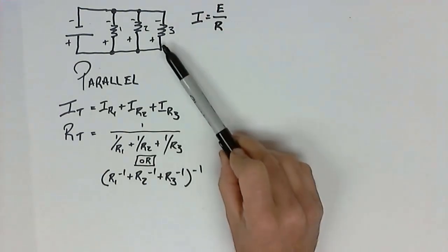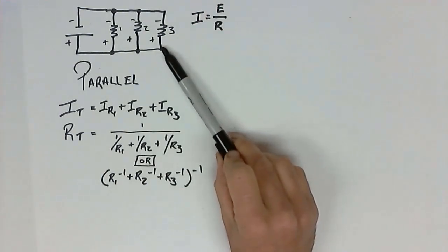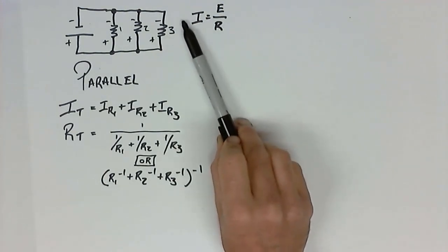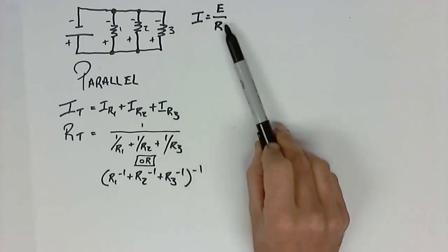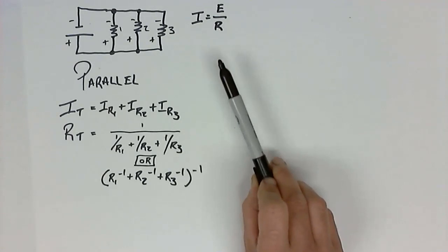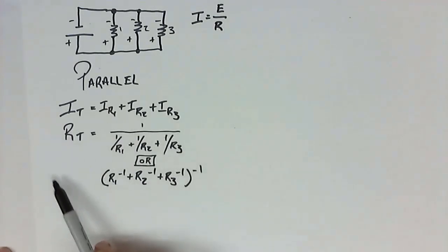If you tell me that you've added more resistors, I know the current has gone up. It has to. If the current goes up, that means that the lower portion of this equation, that variable, must go down. And that's what we see with our total calculation here.